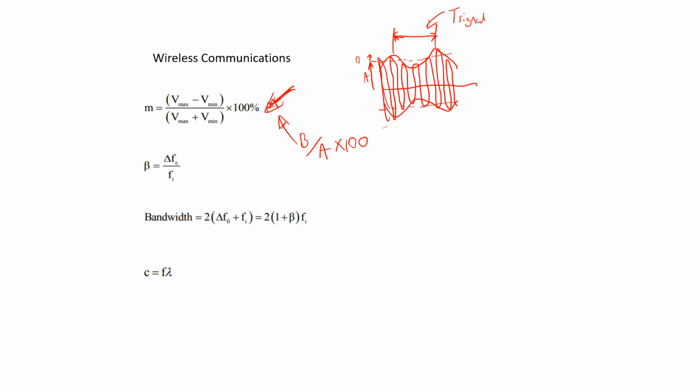And then how many pulses happen in that time will give the time period of the carrier. So if there's 1, 2, 3, 4, 5 happen in that time, the time period of the carrier would be a fifth of whatever the time period of the signal would be, because 5 of them happen in that time. So make sure you count.